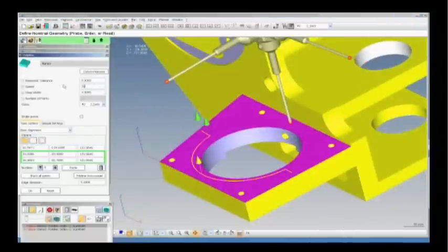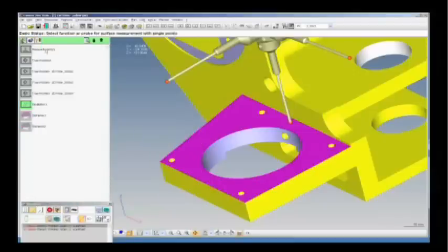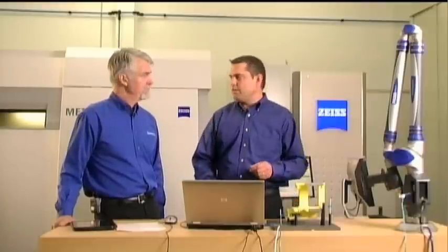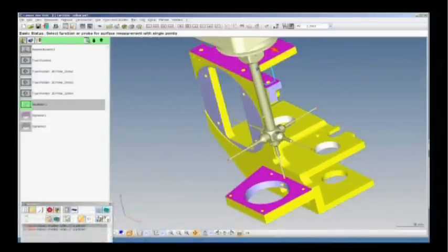So I can actually, in the software, quite efficiently alter the program itself. So again, being object driven, I'm debugging a very specific part of my program. If this was a scripting type language, it'd be challenging to know how to rerun a particular instance. If it's scripting in nature, normally I'd just say, well, start from the beginning and go to the end. Sure. Again, time consuming. Right here, all I'm going to do in Calypso is just highlight the actual parallelism that I'm debugging, and just run that.